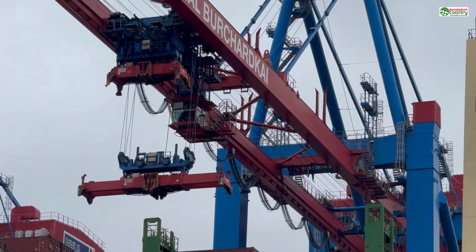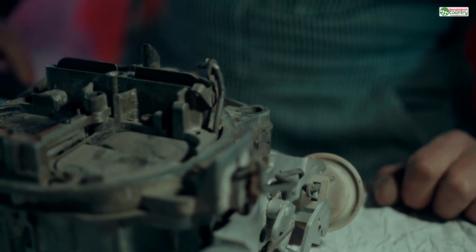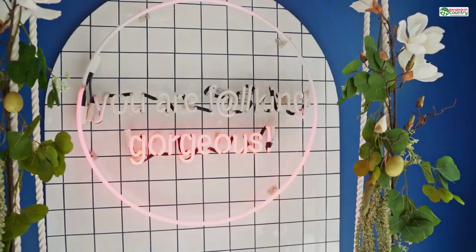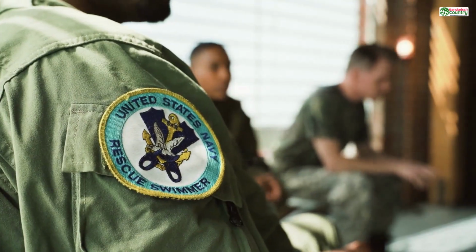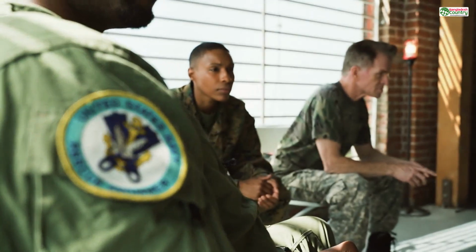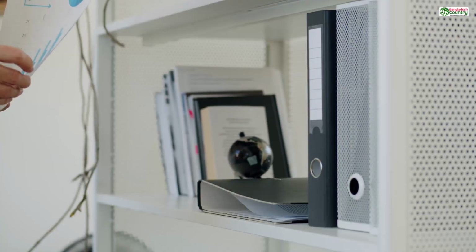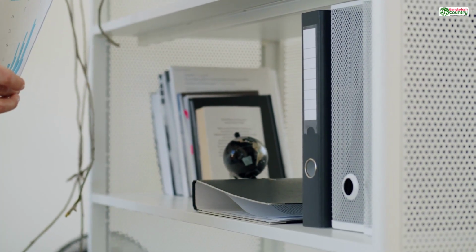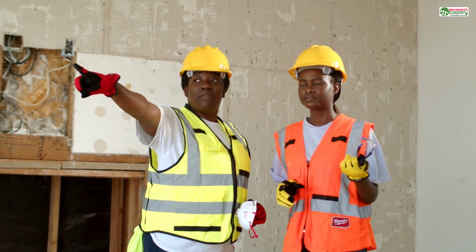But, and this is a very important but, it's not a magic wand. Sometimes the automatic repair can create weird results, especially on very complex or badly damaged models. It might patch a hole in a way that slightly changes the shape you intended. That's why it's critical to understand what it's doing. By diagnosing the file first, you can see the problem areas, try the auto repair, and then inspect its work to make sure the result is still your original vision.